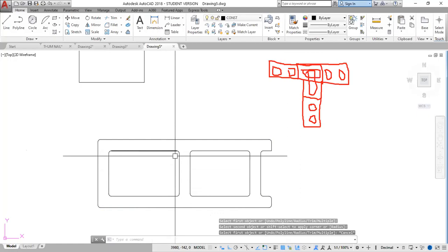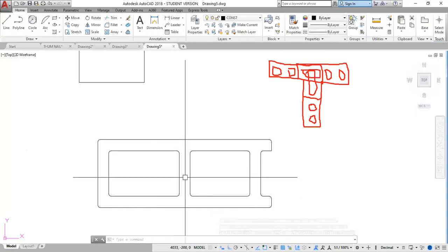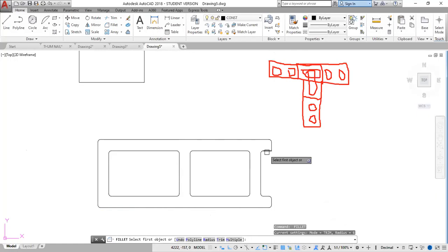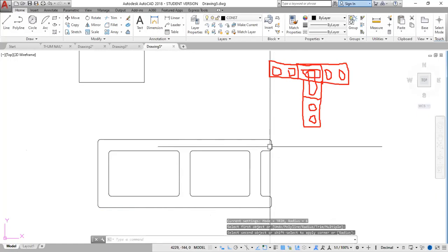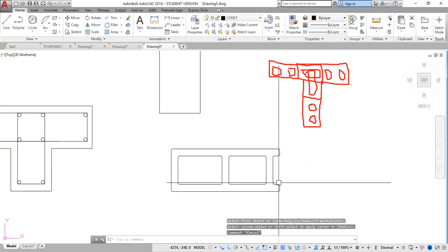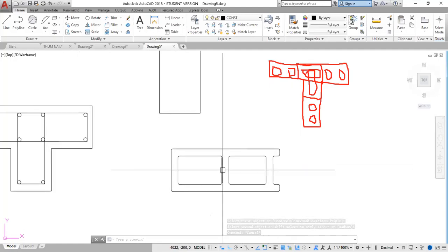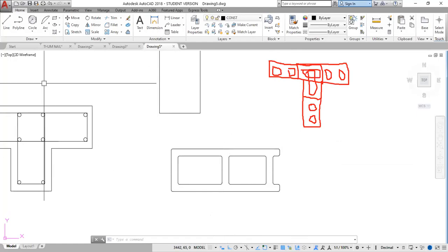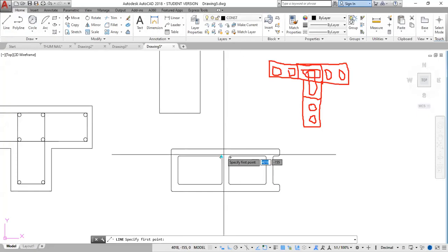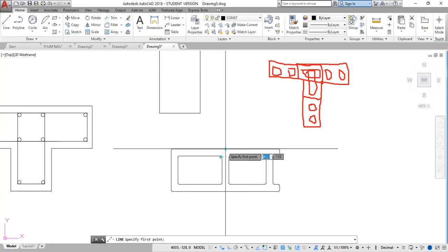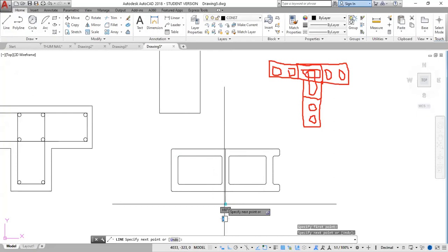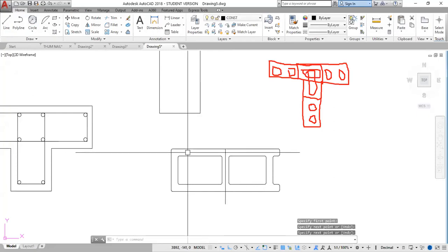Now I probably should cut this here and then mirror this side. Spacebar to reactivate fillet, touch this, touch that also, escape. Now I will need to draw a line through this. So line, L, enter, line here, enter. Now I'm going to trim off everything on this side.